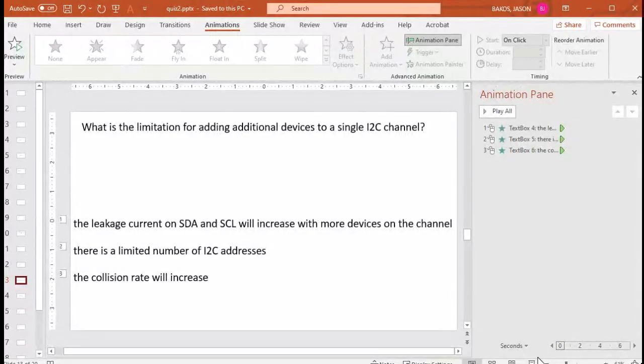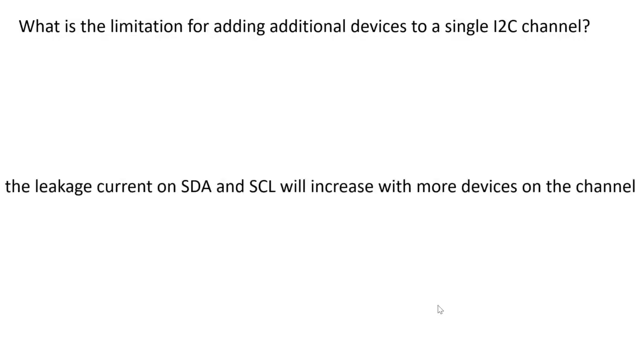That isn't necessarily the case if you're using external pull-up resistors. I think, and I don't even know this for sure, that most I2C devices have internal pull-ups, or you might be able to configure it, but that's still unclear. You have to read the data sheet for the devices that you're using.